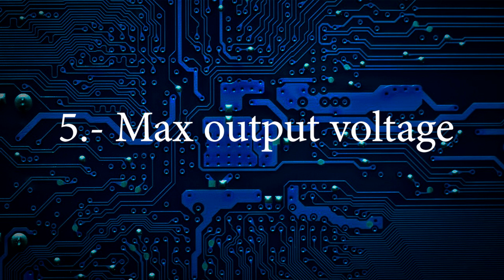Operational amplifiers, like any other semiconductor, have a voltage drop at their output. This value will vary depending on the consumption current, but it is usually between 0.7 volts and 1.8 volts depending on the amplifier model. How does this affect us? We must consider this when designing amplification stages. If our application requires an output that is very close to the supplied amplitude, we'll have problems. Therefore, the power supply ideally should be 1 or 2 volts above the maximum amplitude we want. Let's see this case in the test.